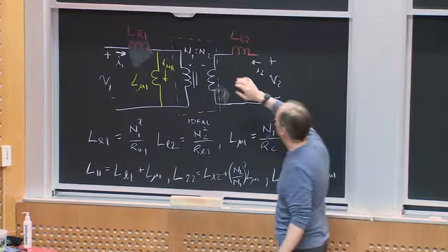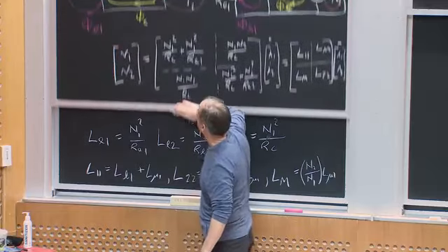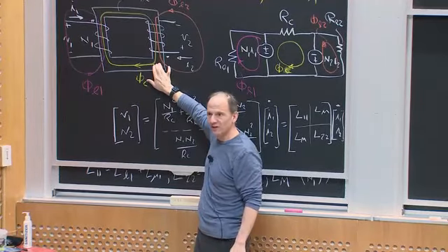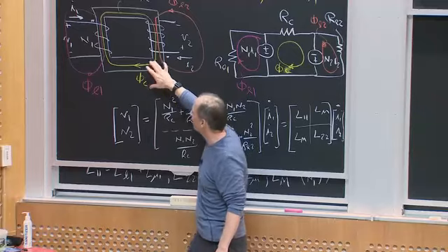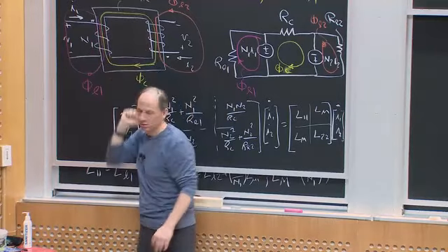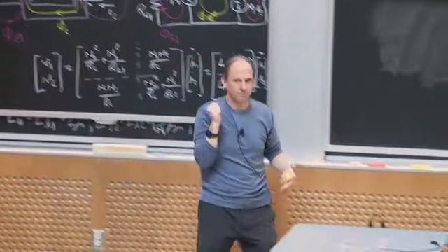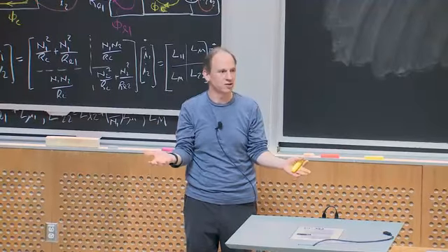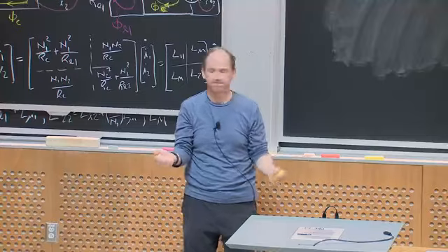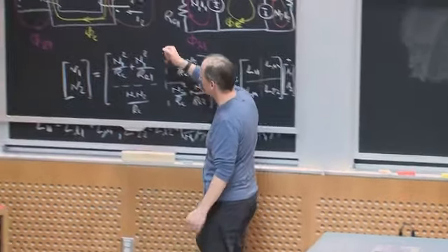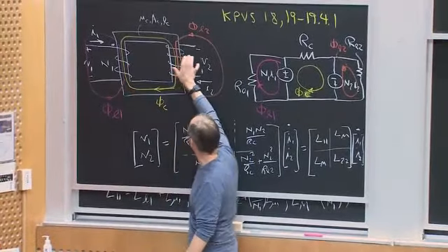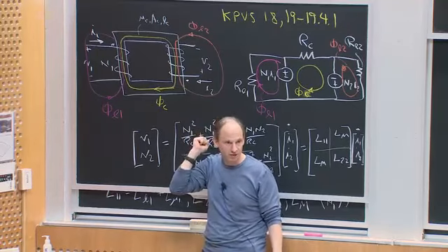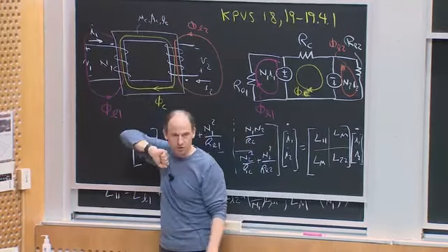If I have only the yellow flux component, if the core is infinitely permeable, the flux density in the core is simply related to the flux and hence the volt-seconds at the windings, okay? And so those would perfectly, the voltage here and voltage here would be scaled versions of one another because they're all just linking the same flux, scaled by the number of turns, all right?